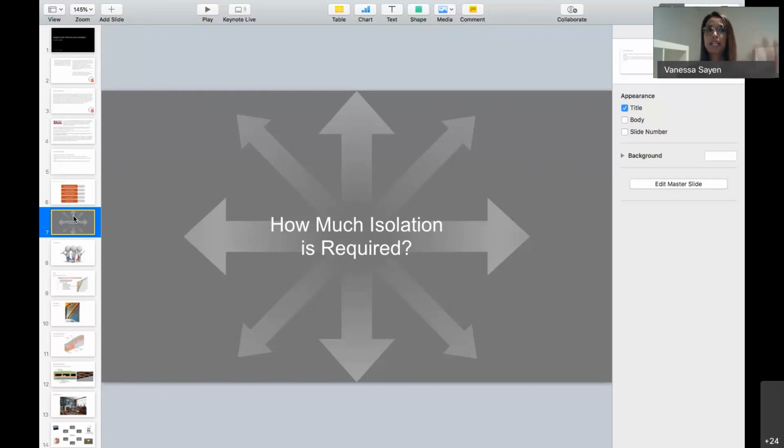So again, it's just an example of how different frequencies travel. In a chamber like this, frequencies will not travel. They're going to be reflecting within these very thick walls, so it doesn't go anywhere else. That's one of the things to keep in mind when we're planning a room: to understand what they're going to be using that space for. Do you want to keep the private conversations private? Then we need to plan ahead to cover those middle frequencies. Is this going to be your home theater room? Okay, now we have to focus on keeping those low frequencies out of the rest of the house.